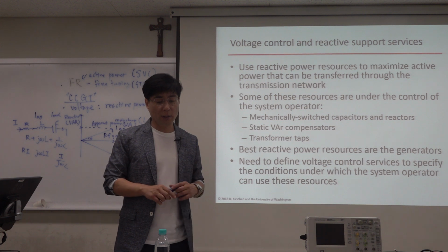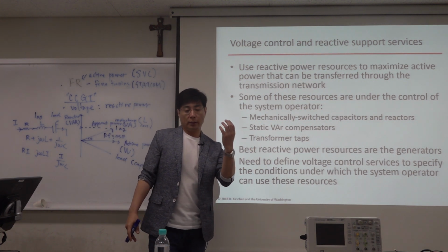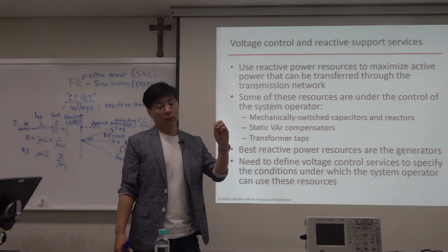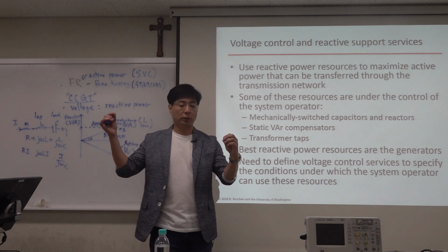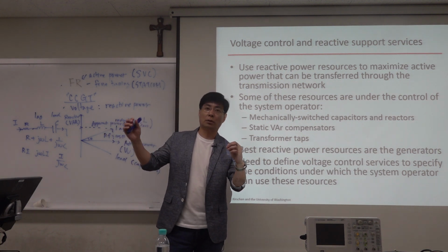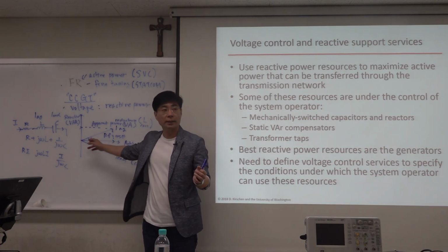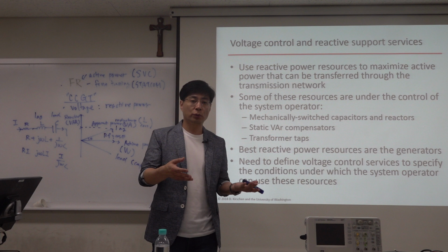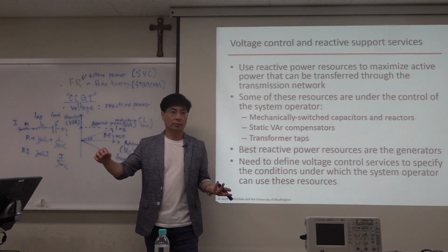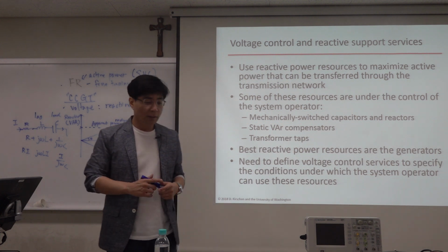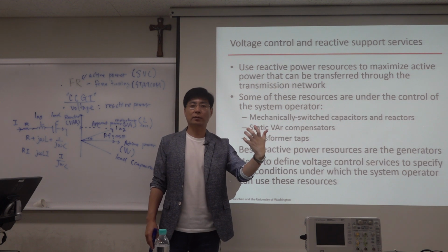And if we assume an ideal thing such that the PV inverters can communicate with each other or can communicate to a centralized controller, then this controller can send some signal so that the PV inverter can change this theta. Then it can contribute to controlling the voltage in the distribution network. Okay, but that's the ideal case, and in reality, this PV inverter does not have communication equipment.